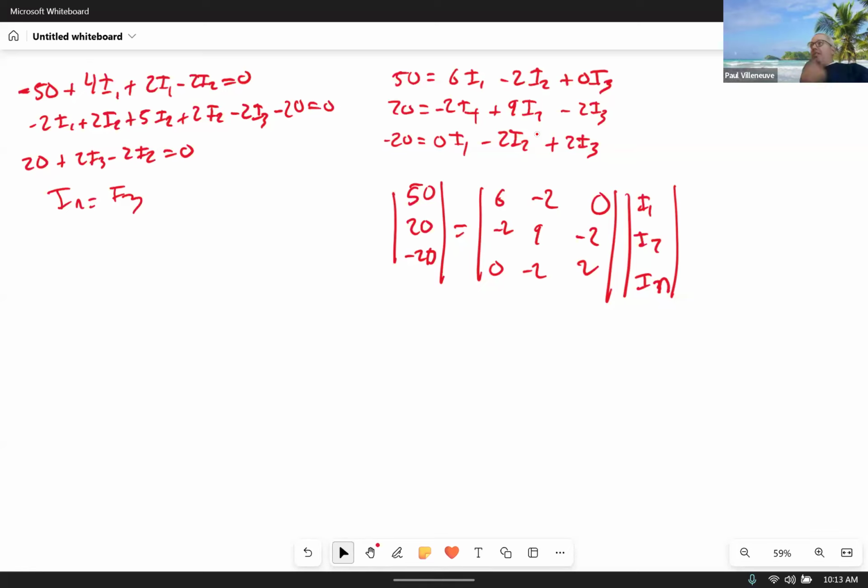So you just put a short circuit to solve for I_N. If you don't like doing that, you can solve for V Thevenin and R equivalent, and then you know that I Norton is equal to V Thevenin divided by R equivalent, right? That's another way to do it, so it might be good to check your work. If you're doing an exam or homework, you can just compare the two and see if you get the same result. Okay? Anything else?